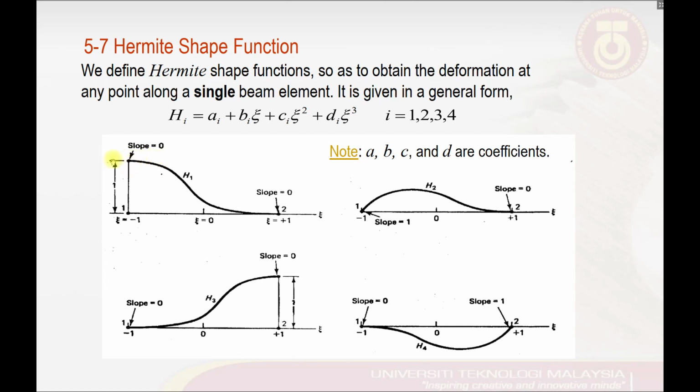It is a flat, horizontal position of the beam at this position, but in terms of translation it has translation. At node number 2, where z equals +1, there will be no slope and no rotation. So this is the purpose of the shape functions. Between the 2 points, the variation will look something like this. It is no longer linear.